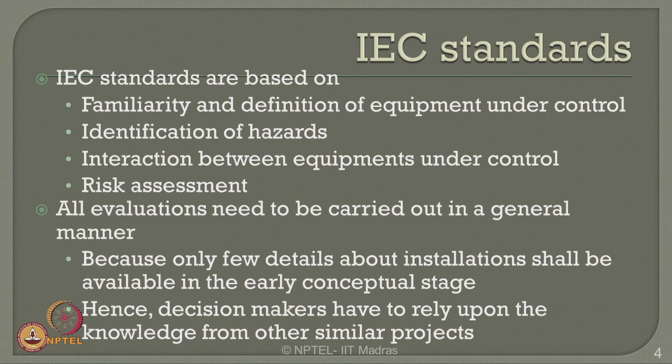Only a few details about the installation will be available to you in the early conceptual stage, because when the process starts, as the process becomes complex because of the operational temperature and pressure variations, it is very difficult to foresee the hazards in the beginning. So, you will have only very few details about the installations, which will talk about the mechanical configuration specifications of the equipment, the working principles, working temperature and pressure, etc. In case pressure and temperature are violated during the operation or during the process, you will not have much detail about these installations at those high pressure and temperature conditions.